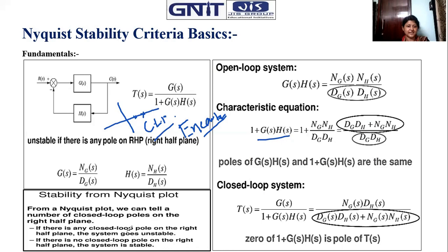While the open loop is made into closed loop, this concept should be there. The open loop pole position is fixed, but the closed loop pole position can change with respect to the system variable, right? So the modification is done in the closed loop pole positions.